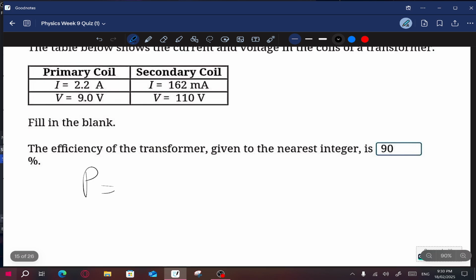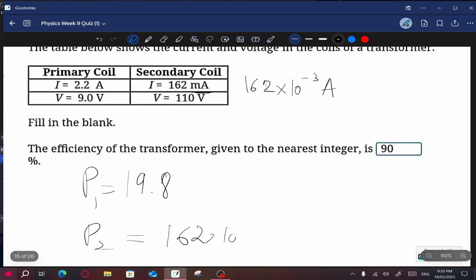Okay, now the peak voltage. Remember, we said that the RMS is the peak over radical 2. So the RMS is 12, and we don't know the peak. VP over radical 2, so VP is equal to 12 radical 2, which equals 16.97 or 17.0. It's fine. Here they did 16.8, but I think they used 1.41 or something. They didn't use the exact value of radical 2, which made them get a lower answer.